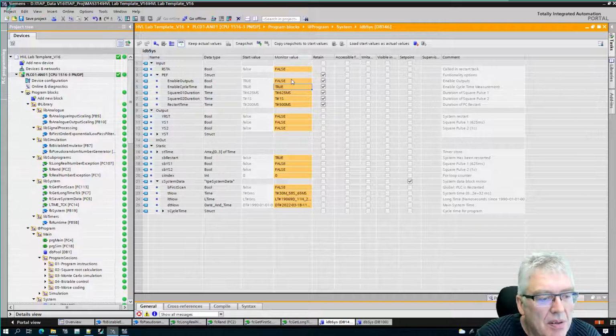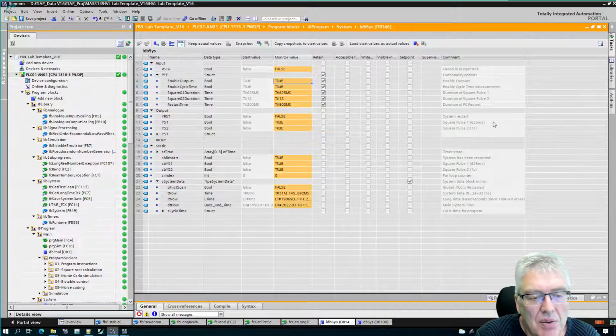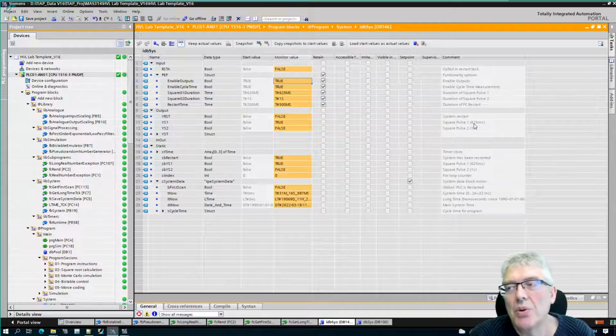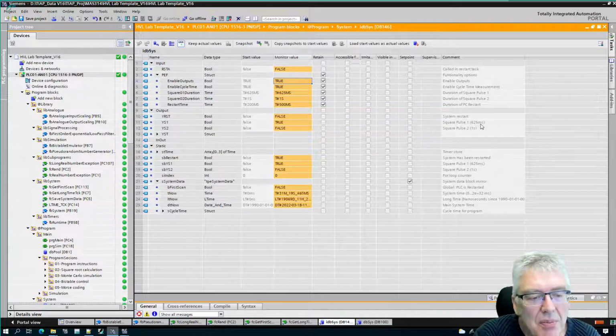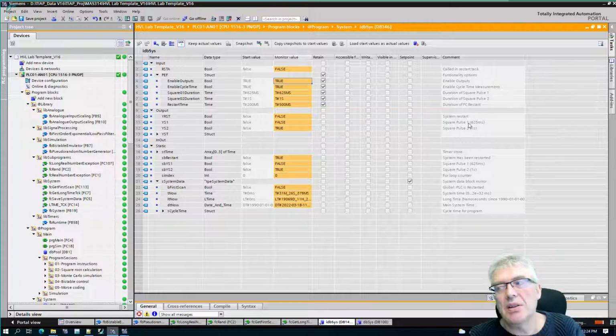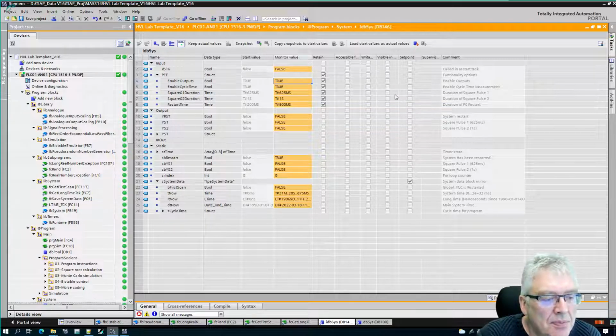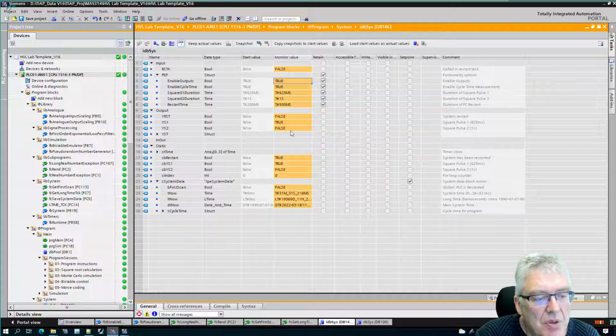I have to hit. Then that's the cycle time measurement, and now the outputs turn back on. So these are two square wave signals. The first square wave is alternating, or the frequency is a high and low. Duration is 625 milliseconds, and the other one is 1 second. This duration here is defined as something called fast flashing, and the 1 second you could use for timing.